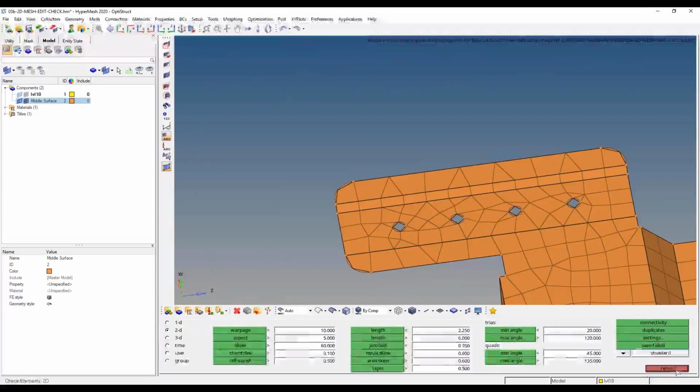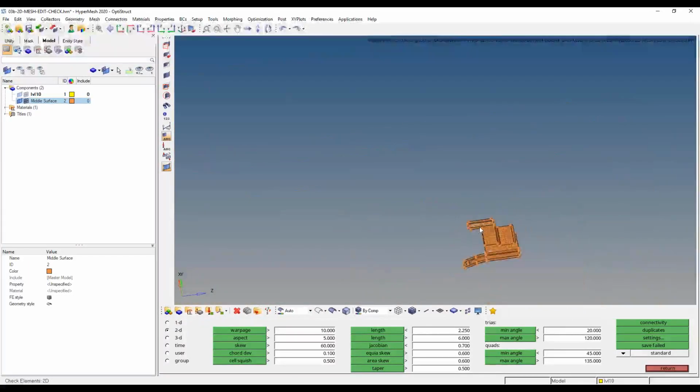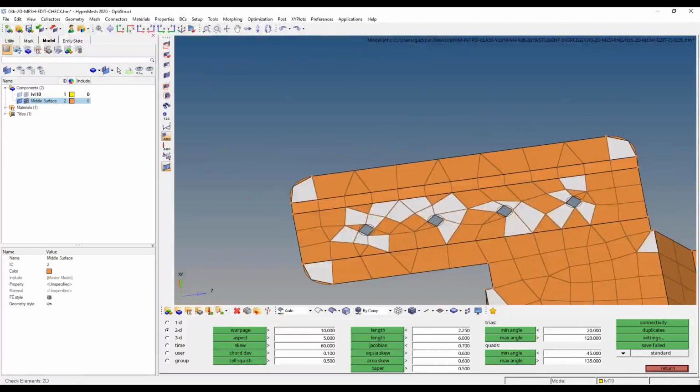And why I wanted to save that one there, it didn't quite break here, but we'll see that those bolt holes, if they're too small relative to the element size, they really tend to give you some low quality elements in either the aspect ratio or Jacobian. And here we're seeing that there's a good handful of my elements failing at that surface.